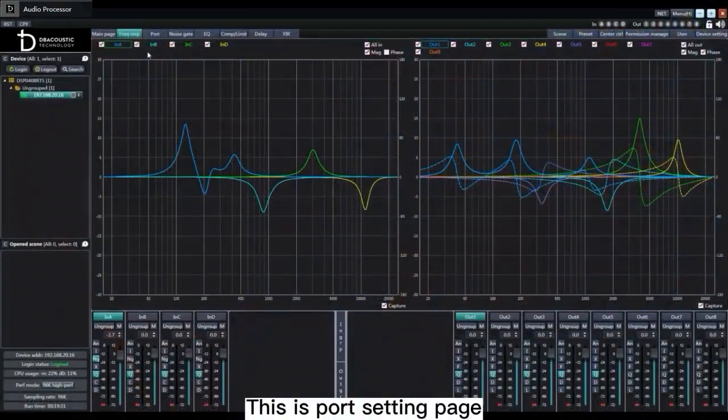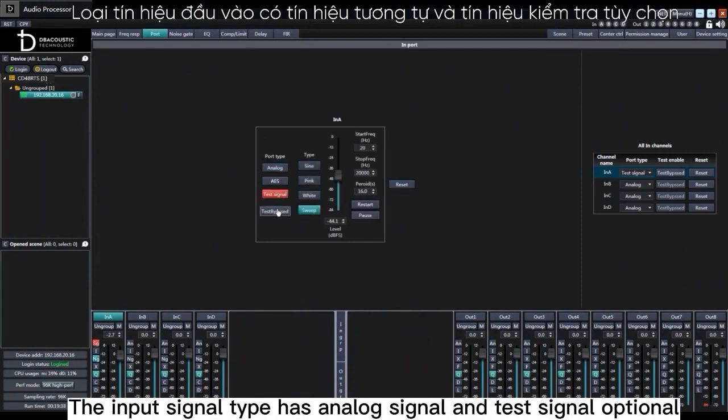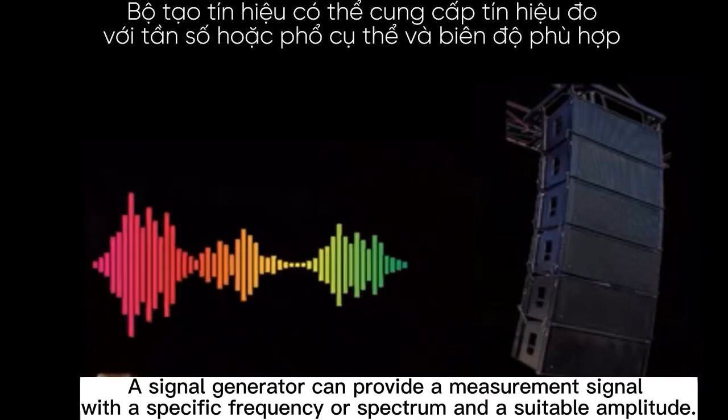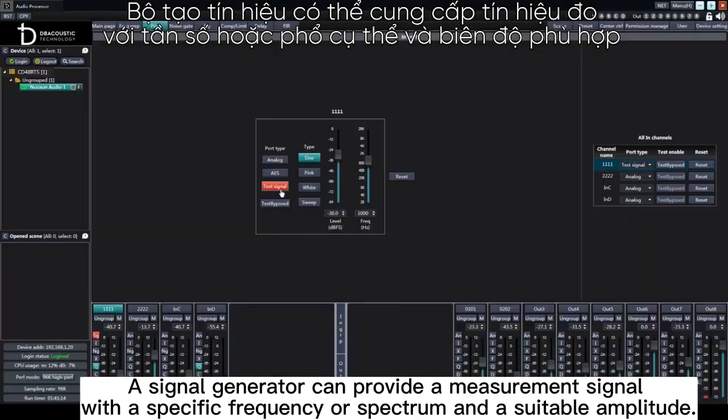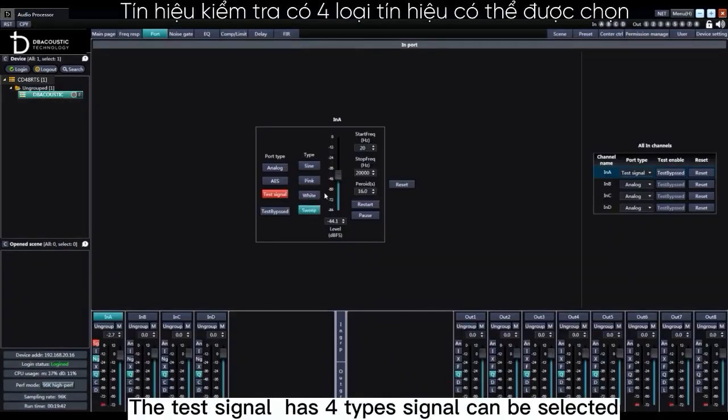Port setting. This is the port setting page. There are input port setting and output port setting. The input signal type has analog signal and test signal optional. A signal generator can provide a measurement signal with a specific frequency or spectrum and a suitable amplitude. Before enabling the test signal, complete the routing settings to complete the signal test. The test signal has 4 types.